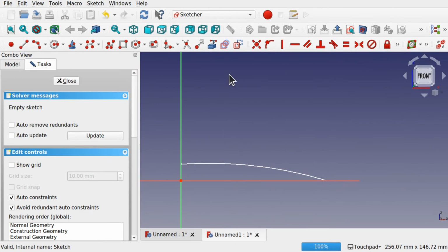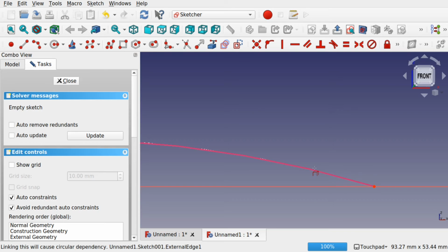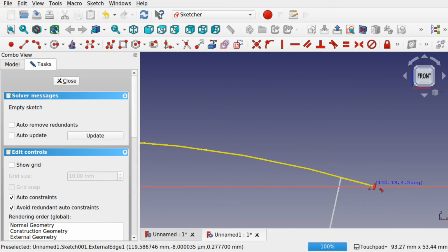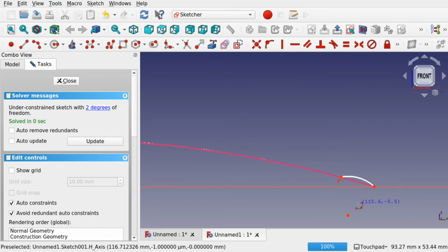Okay, we'll bring in this arc, link that to external geometry. We'll create an arc now. So endpoint and render point arc, connect those up. Just bring that above, don't make it tangent, otherwise it's going to connect to this arc and the points will probably fly over to the left. And we'll adjust that and see if we can adjust this. And just pull this out.